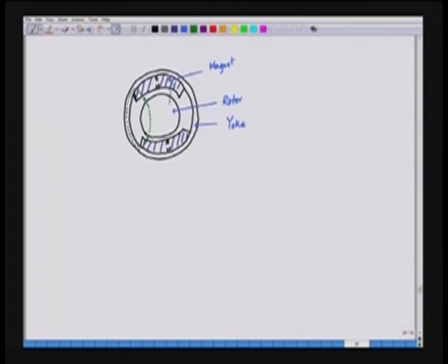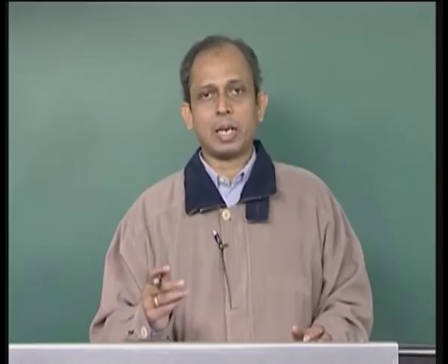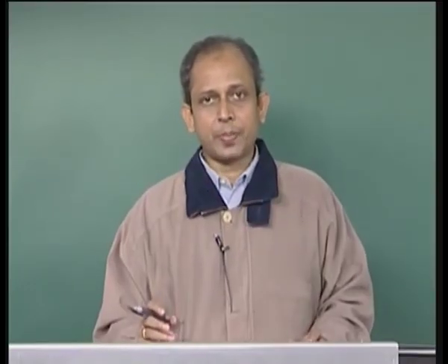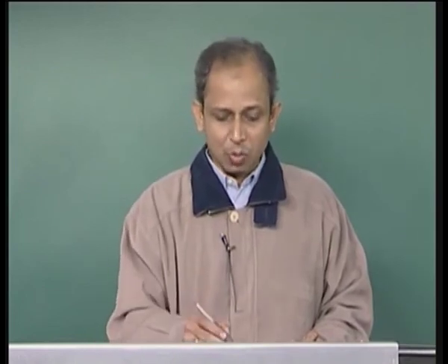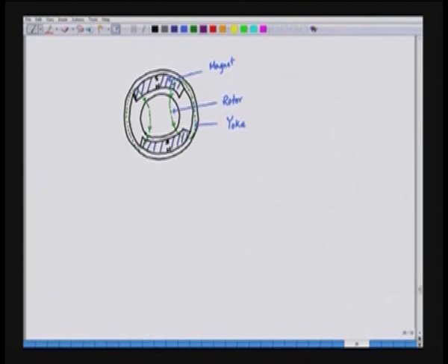Similarly, we can have another flux line here. So, it is coming out of the north pole and entering the south pole. So, this is basically a typical field structure using ferrite magnets, and in ferrite magnets the magnets are basically short, but the width is large here. This is the width of the magnet, so that the cross sectional area is large here, but this length, Li, is small here, and this is to maximize the BH product we are having this magnet.